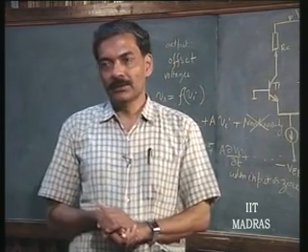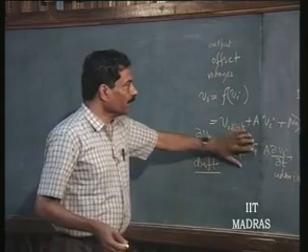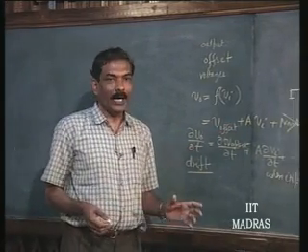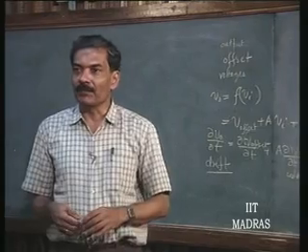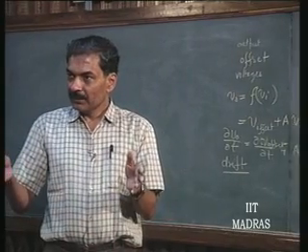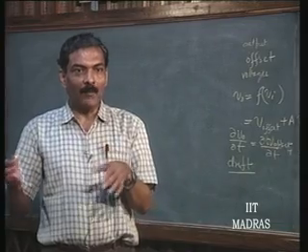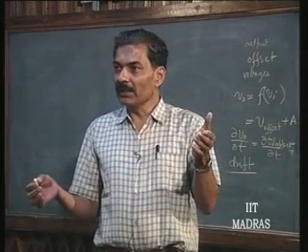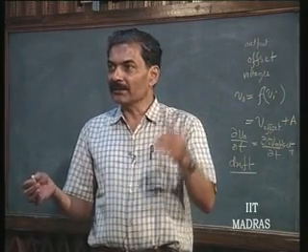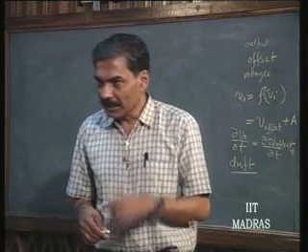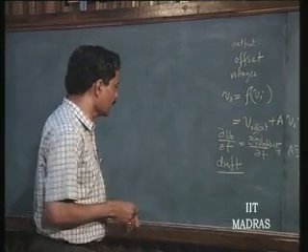So, this has to be eliminated, particularly in situations where you are designing high gain amplifiers. This might drift the output quiescent point to such an extent that the operating point goes to nonlinear regions, and linearity itself or the gain itself gets reduced. This also is a danger. So, therefore, offset has to be reduced considerably.